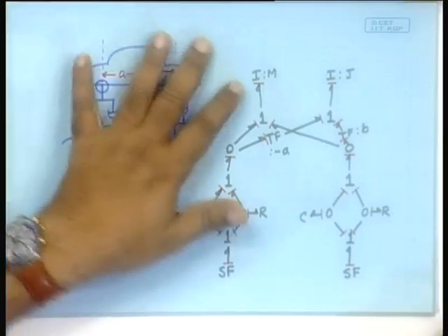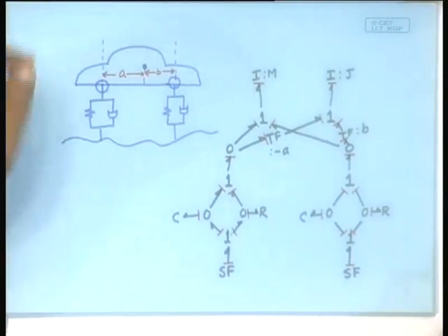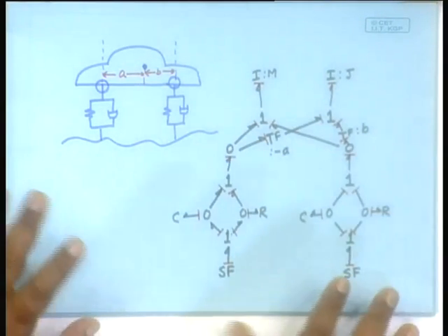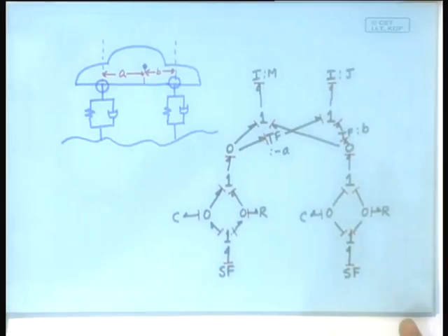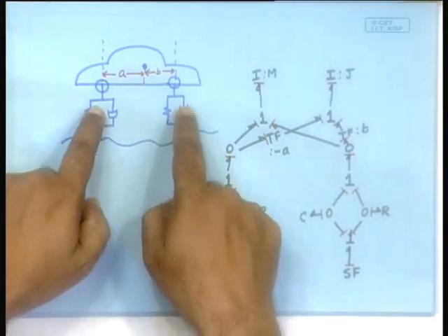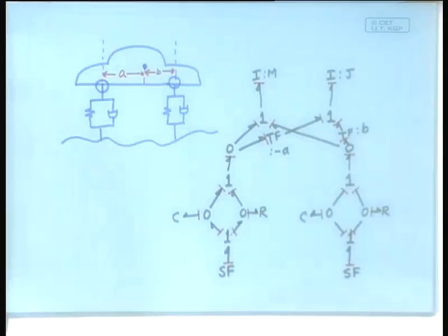So, even this kind of relatively complicated thing which has two different types of motion in the same body, we can represent like this. And in fact, if you obtain the differential equations from this, if you simulate this, you can easily obtain how a specific car is going to bounce. And this is actually done in industry in order to find out how these things should be tuned, so that there is a least amount of bumpiness.